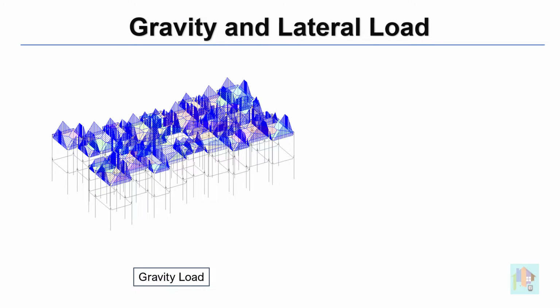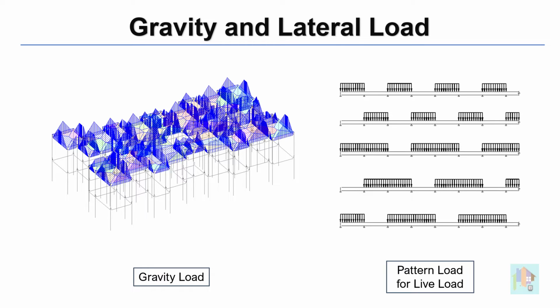For any gravity or lateral load, we assume that the point of application remains constant over time. For example, the self weight of a floor panel is applied as an area load over the entire panel, and at any time, this load application area remains the same. For imposed load, though it is linked with the usage and occupancy which might change over time, still we apply this load over the entire usable area or consider skip loading with a fixed pattern. None of these load application points or zones is affected over time.